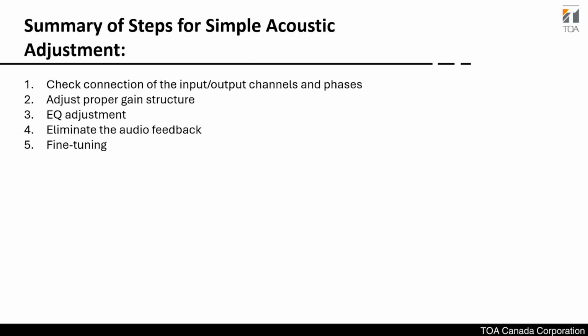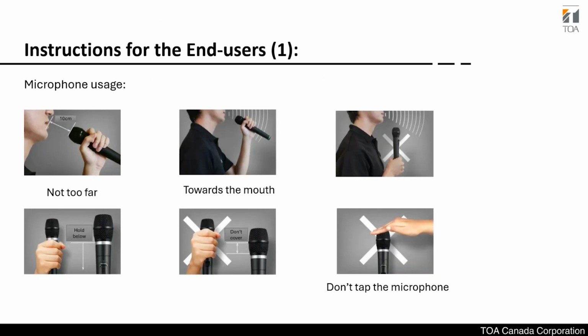So here is the quick summary. Check the connection, adjust the gain structure, do the EQ adjustment, try to eliminate all the audio feedback, and do some kind of fine tuning by adjusting each particular frequency by cranking up the dB, cranking up the level. So you will be surprised.